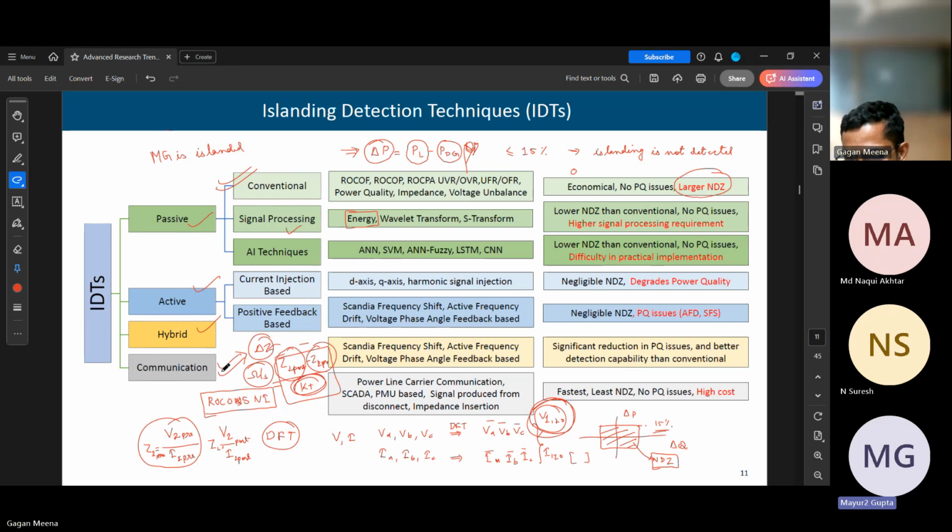See, now you came to the point where we are stuck. There can be storage, but it's not so easily integrated. We don't even mind having gigawatts of storage, but the inverters are very complicated to detect islanding, and then to make them work. Now, in which mode will they work, whether grid-following or grid-forming mode?